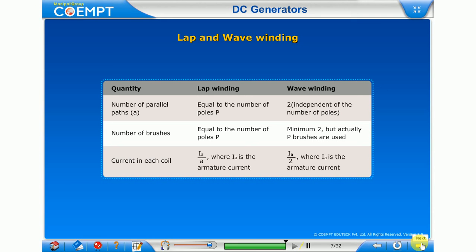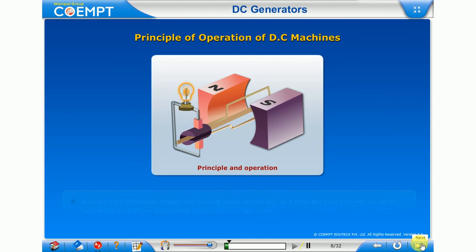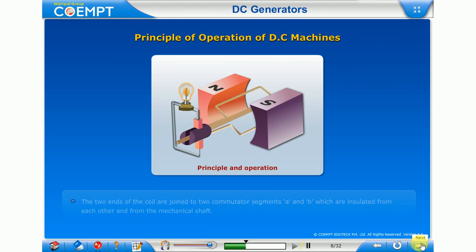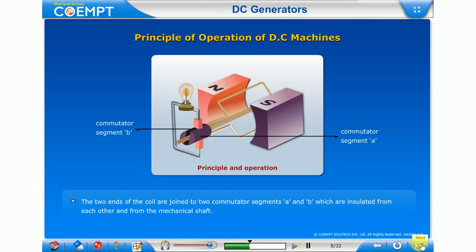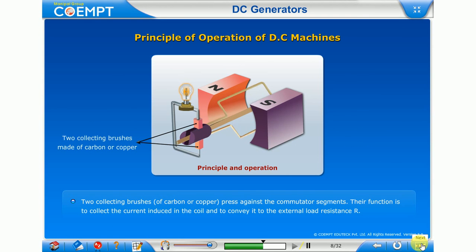From 90 degrees to 180 degrees, the flux linked with the coil gradually increases, but the rate of change of flux linkages decreases. Hence, the induced EMF decreases gradually in position 5 of the coil, where it is reduced to zero value. From 180 degrees to 360 degrees, the variations in the magnitude of EMF are similar to those in the first half of the revolution. Its value is maximum when the coil is in position 7 and minimum at position 1. But it is found that the direction of the induced current is the reverse of the previous direction of flow.